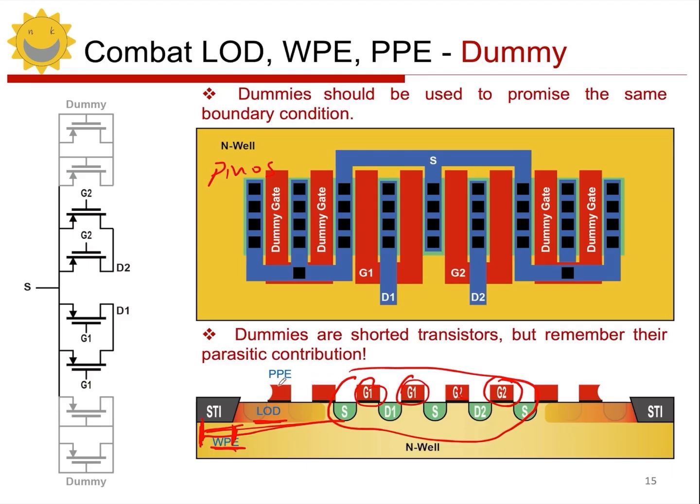You can see this. What about the left side? Because there is no gate on the left side of the gate without the dummy, its etching speed will be faster. So the gate will become narrower, right? This will also become narrower, but the other parts will not change. Pay attention here. In my diagram, when I say this thing is recessed, it refers to the polysilicon proximity effect, which affects the etching speed. It's not caused by the side etching, right? The side etching exists for all these gates, and of course they all have the same side etching issues. The side etching is the same for all of them, including this one, which also has side etching, right?